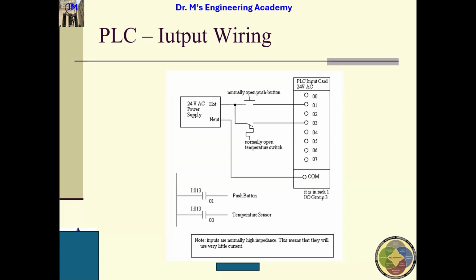This is different from a hardwired system. For our first lab, I taught you how to hardwire this system, so you need to connect bit by bit, terminal by terminal. But for the PLC, you need to connect all the inputs to the PLC, and all the outputs to the PLC. You should never ever connect the inputs and outputs together when we use a PLC. This is very, very important.